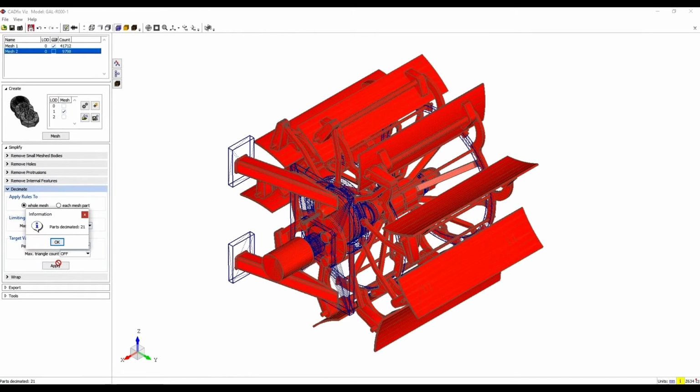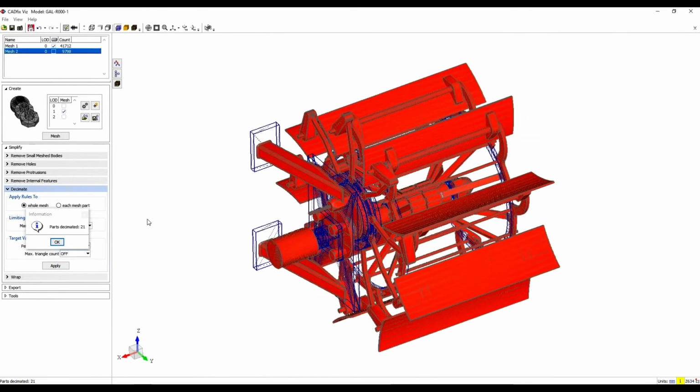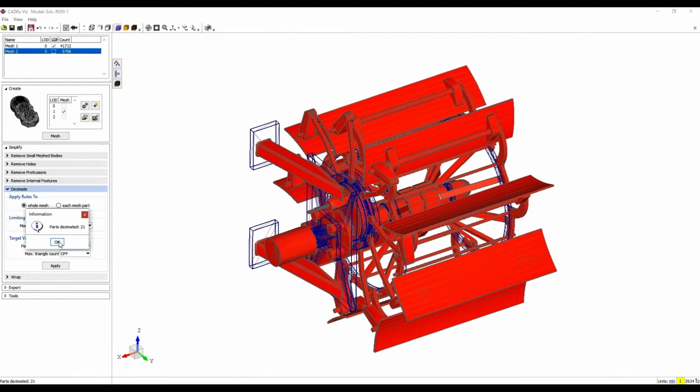They're highlighted in red on screen. As you can see, we haven't decimated all the parts just because those components couldn't have been decimated within that 0.1 millimeter tolerance. And we've reduced by just a couple thousand, so not up to the 70%, but that's because we had that safeguard of that maximum geometric change to stop us from oversimplifying our model.